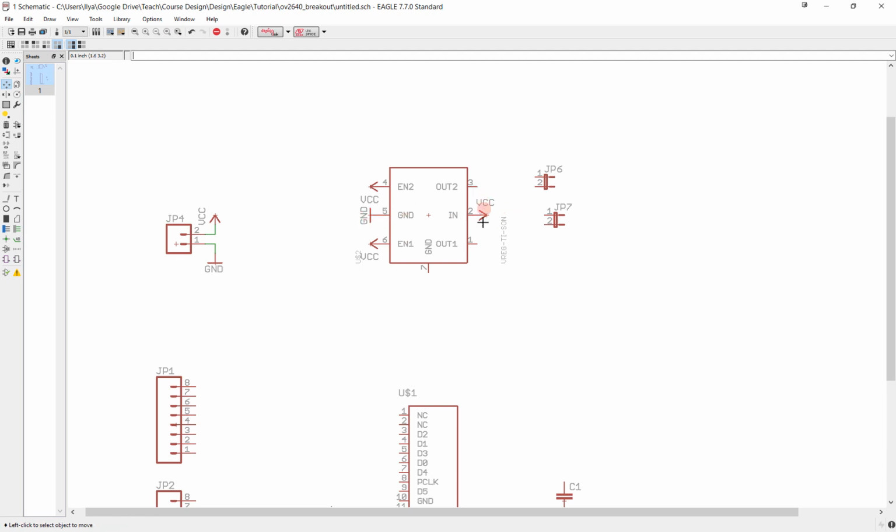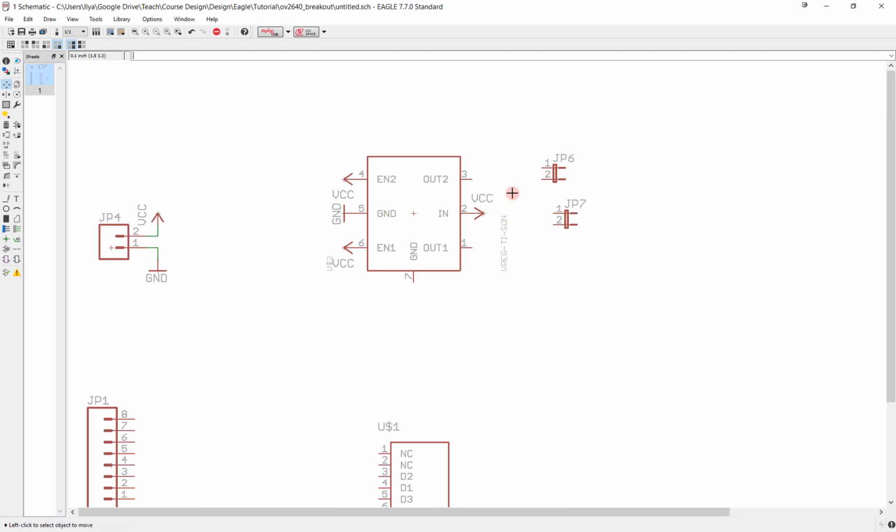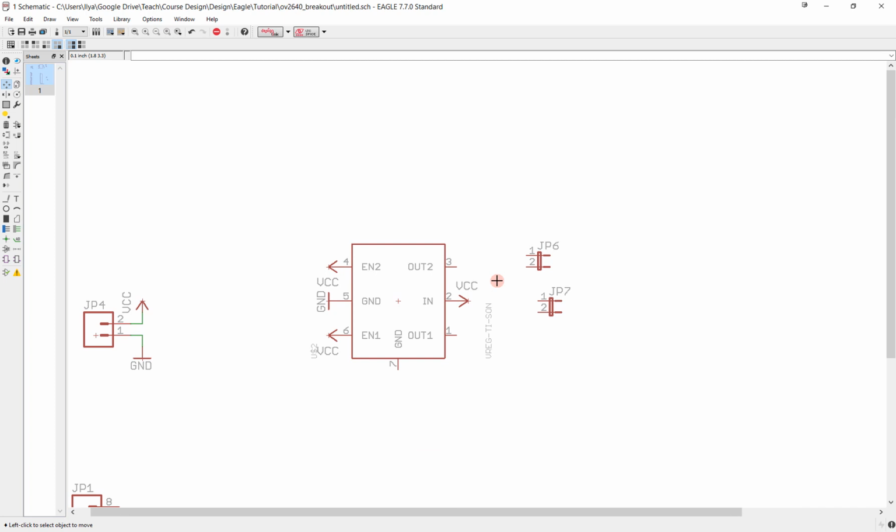and two outputs. Now, as I said, this camera takes 3 voltages, but 2 of them can actually be the same, and I'm going to provide them with the same one. But again, it doesn't have to be, and optionally, I want to give the user the opportunity to provide all 3 different power supplies. That's why I'm going to be using these jumpers. And so the first output here is going to be 3 volts.